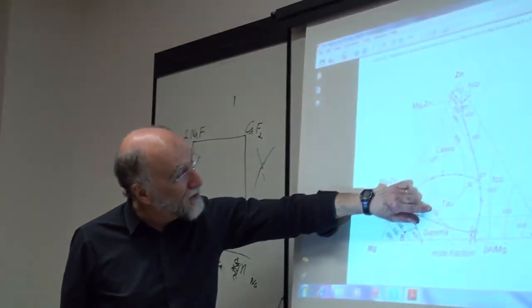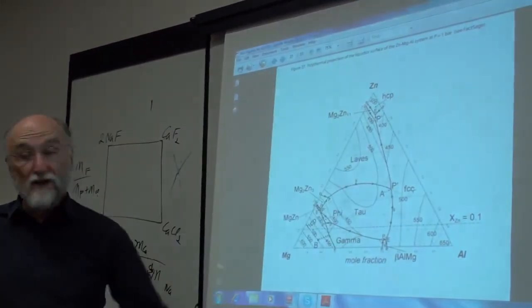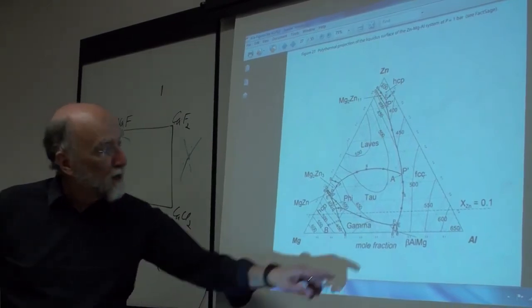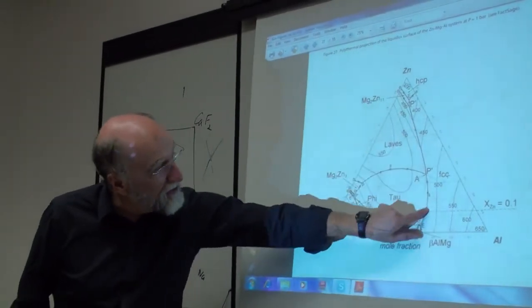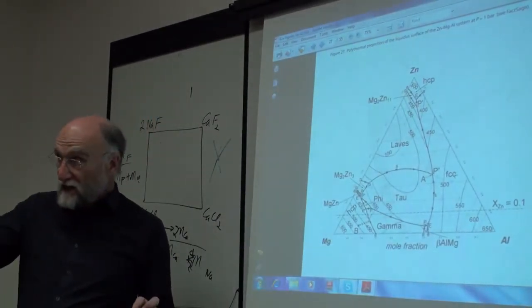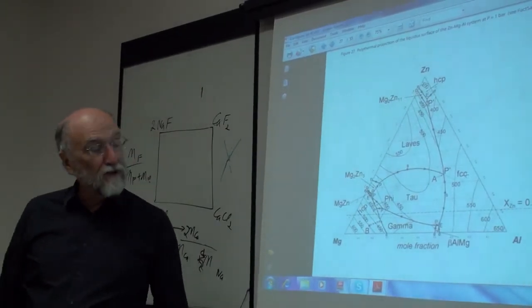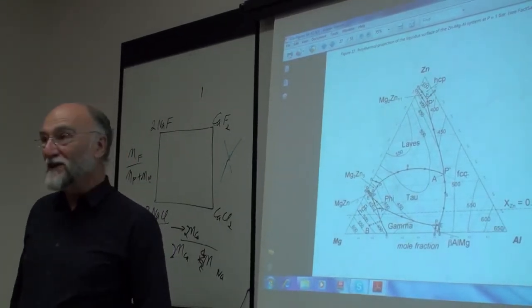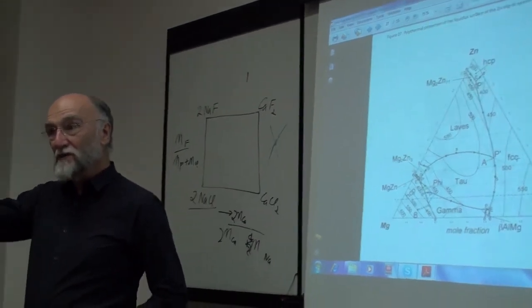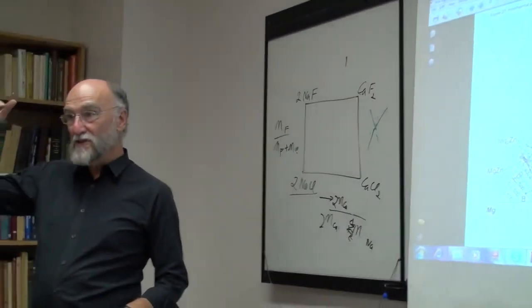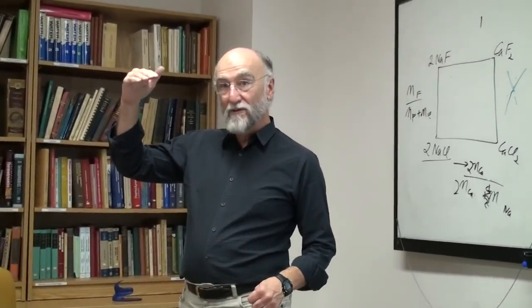It puts on the isothermal lines. Of course, each isothermal line is just an isothermal section. But the univariate valleys, you'll see it calculating the univariate valleys. The univariate valleys are a second calculation, which is actually a double zero phase fraction line. Remember, you go along a zero phase fraction line, you keep the amount of one phase just equal to zero, in equilibrium with other phases.